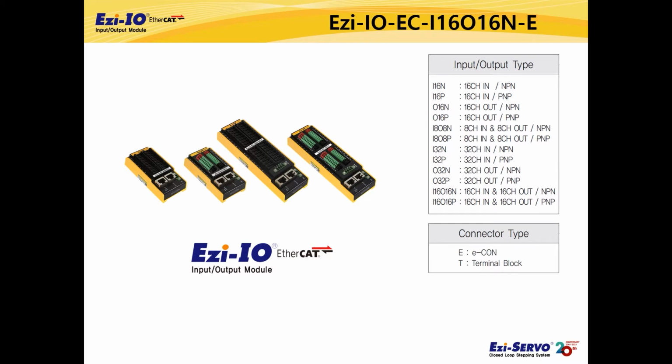Ezi-IO EtherCAT has 2 options, 16 and 32 channels, and it is possible to select input alone, output alone, or mixed input and output. For example, I16N model supports 16 input channels only, O16N model supports 16 output channels only, and I808N model supports 8 input channels and 8 output channels together. And there are 2 types of selectable connector, Econ and terminal block.